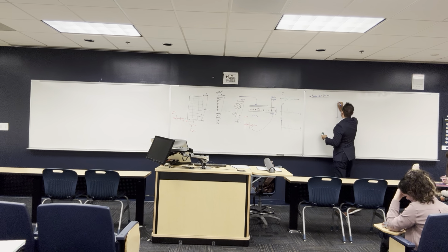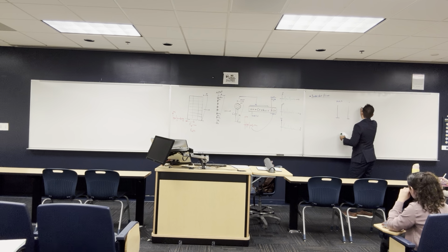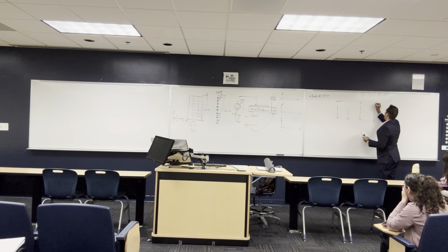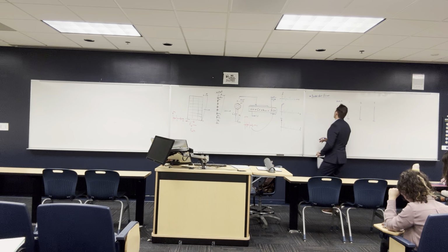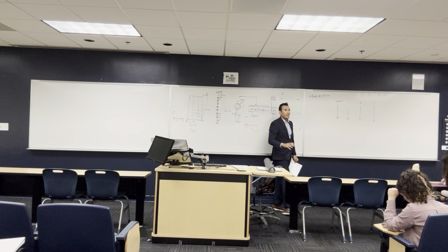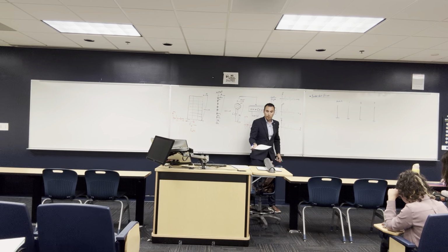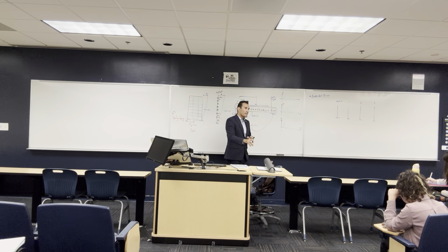Let's say this is mode shape number 1, and this is mode number 2, 3, let's put up to 4. Mode number 1 is the easiest mode, the mode shape, the shape of the building that is gonna move. And the second is the second easiest.